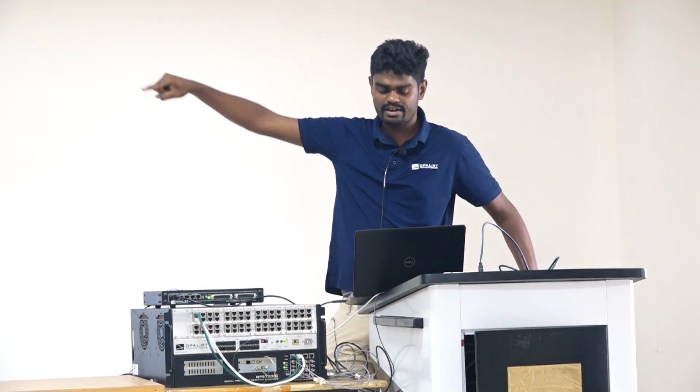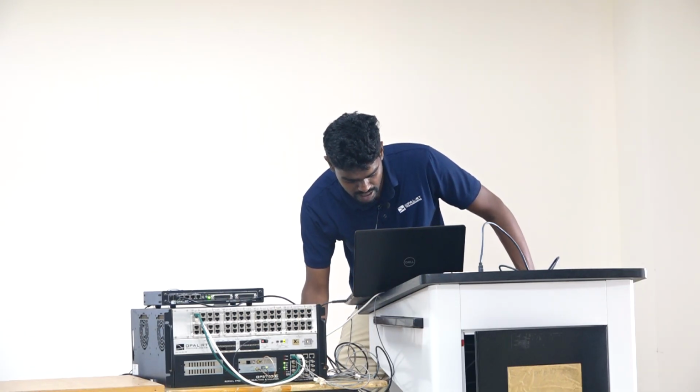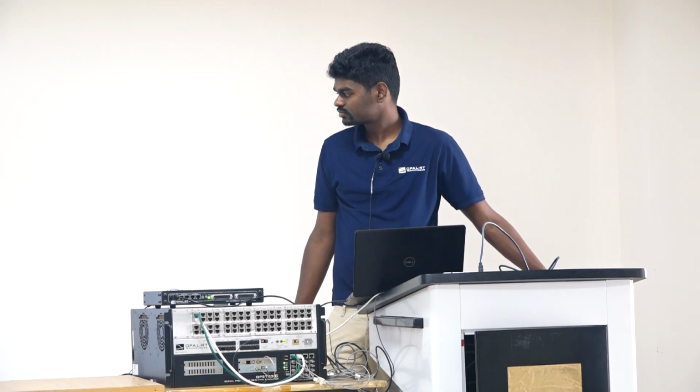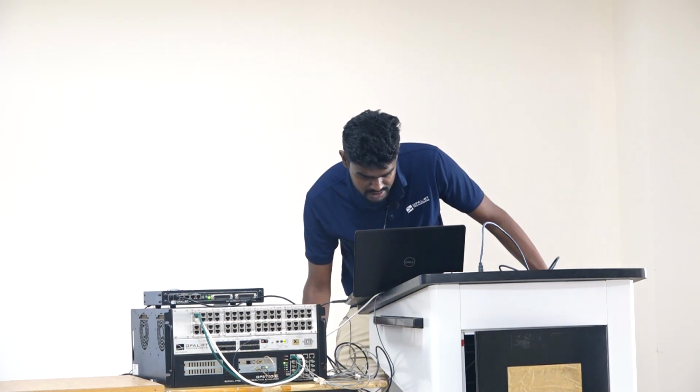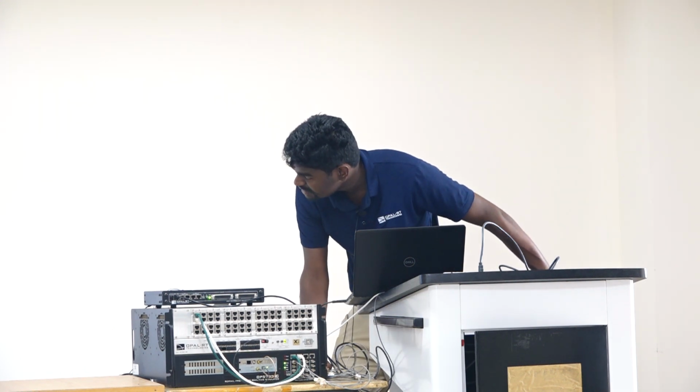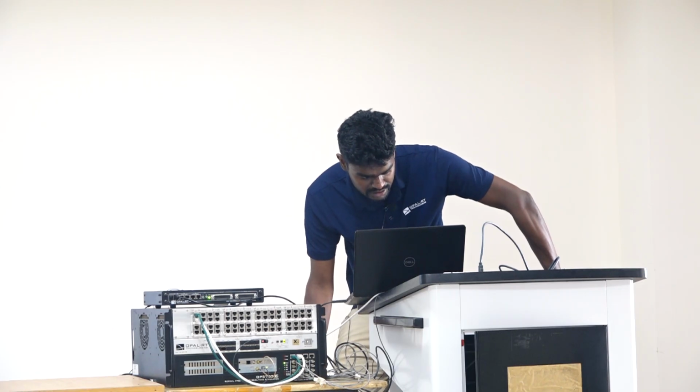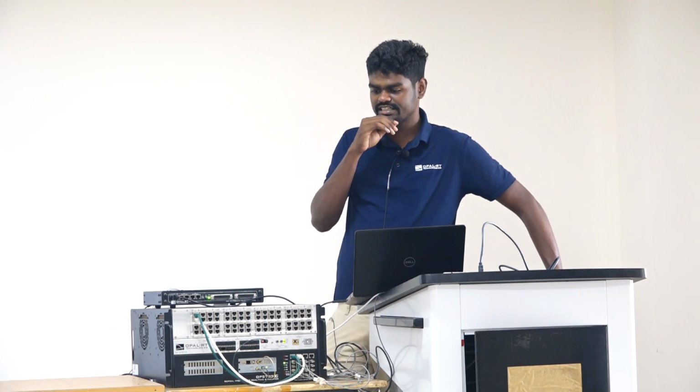There are two ways to monitor. You can either monitor it through the scope which you have here, or you can also monitor it through RTLab. Maybe I'll show you that first. Let the scope open. You see the voltages and currents. You can see the sine waves here. You can also monitor it through software from RTLab called ScopeView. Normally I use that for seeing it. Now I'll launch that and I'll show you all three results: the grid current, grid voltage, and also the inverter's current. All those three we can see now.